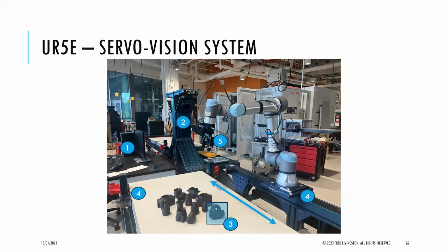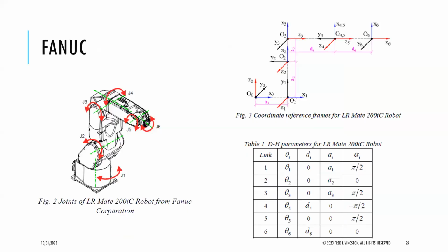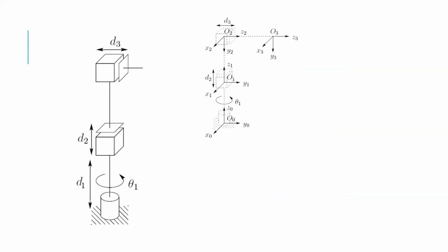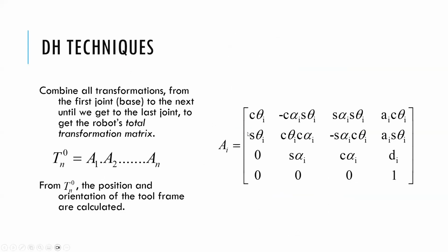And so our controller usually does the math for you, if it's a nicer system like the UR series. But if you're building your own robot system with some servo motors and a microcontroller, you could do this math yourself. Even on a Raspberry Pi, if I hard code it in, I still just do cosines and sines.